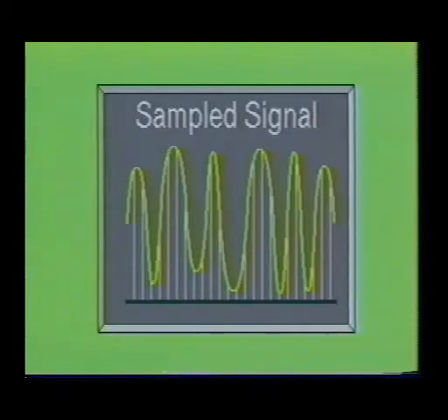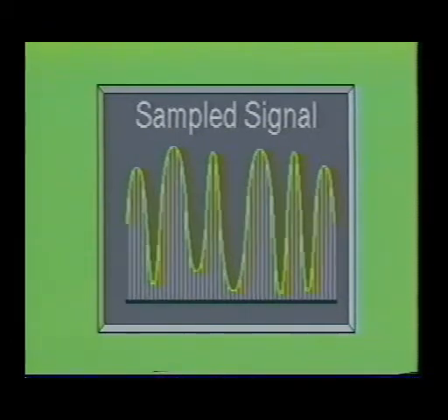Here you see a sampled signal. If an analog signal is allowed to exist only at certain discrete instants in time, a display such as the one being shown to you now will show the instantaneous values of the measured signal. The magnitude of the individual signals can represent any value within the imposed limits. The time limit of this signal might be measured in milliseconds or microseconds. If the time limit was marked off in units of milliseconds, there could be up to 1,000 samples per second.